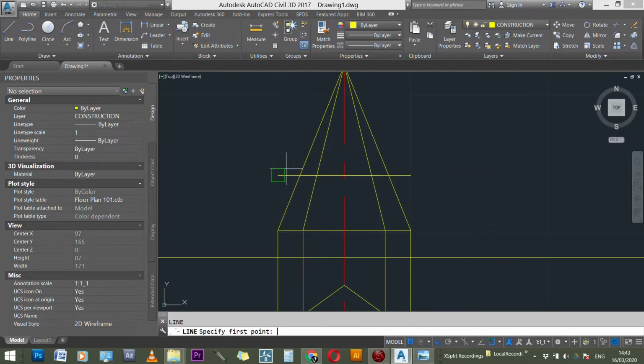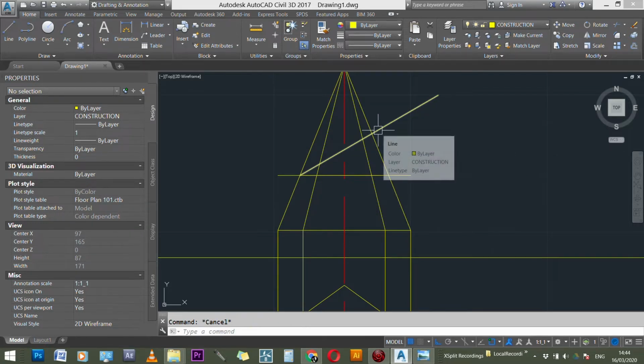I don't have my settings set up like that. So I'm just going to pull my line out, and I'm going to type in the less than sign and then touch 30 degrees, and that gives me my 30 degrees. On some of your PCs, you can actually hit L for line, and then while you're drawing the line, you can hit tab. So you just project a line at any distance you think is going to be long enough. Then you can always go back and trim, hit tab, and then punch in 30, and then hit enter, and that's how you get degrees. But on mine, I actually have to use the less than sign.